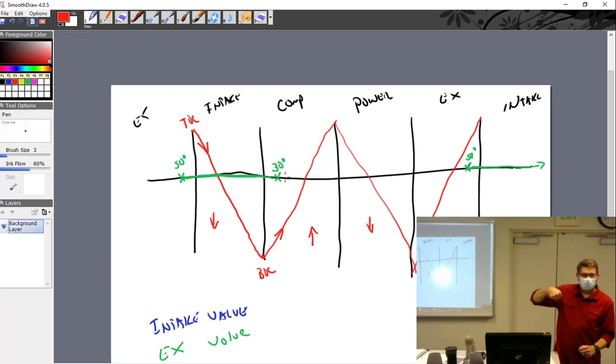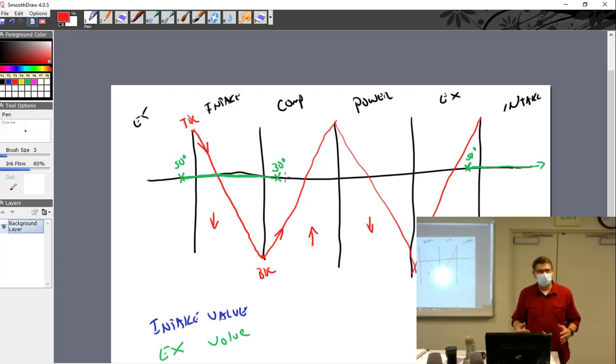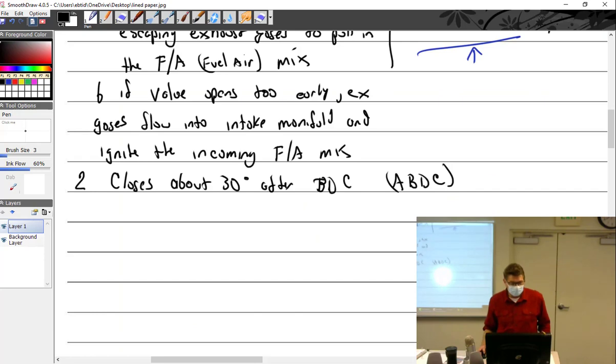But I'm still pulling back on it. And I could even start pushing forward a little bit maybe, and it would still have some vacuum in there and would still actually come in. So that's what's happening. Even though the piston has sucked as much as it can, it's turning around. What's above it is still lower pressure than the intake manifold, so let's leave it open until the two equalize. So leave it open a little bit longer, a little bit more fuel-air mixture into the bucket.